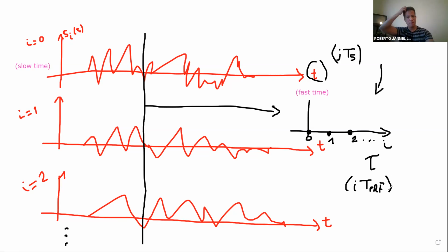If I'm doing the same thing for the fast time, then why should I treat the slow time differently? It's easy to see why, of course. In the fast time, you have a whole bunch of samples. In the slow time, you have a few. That's probably why we're always reminded that the slow time is discrete sampling. But the fast time is discrete sampling too. So we call this tau, and we have a signal versus tau, which is the slow time.